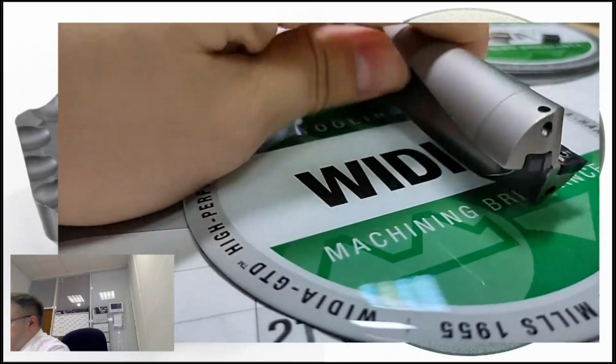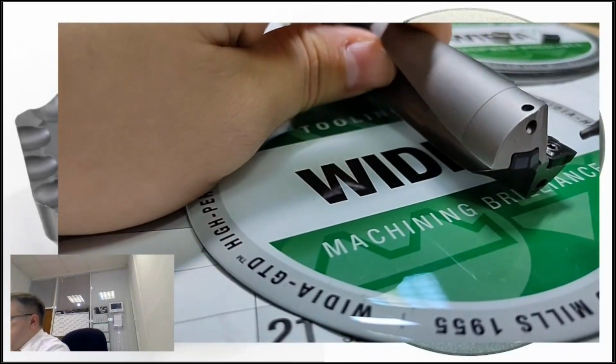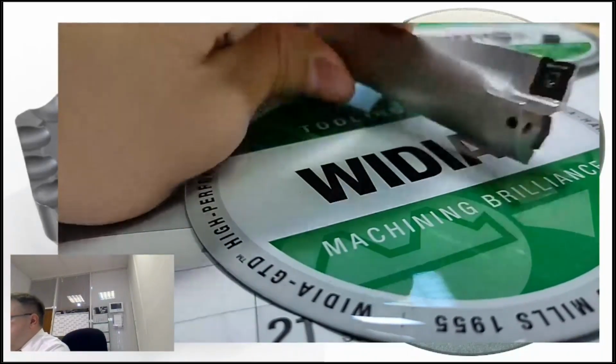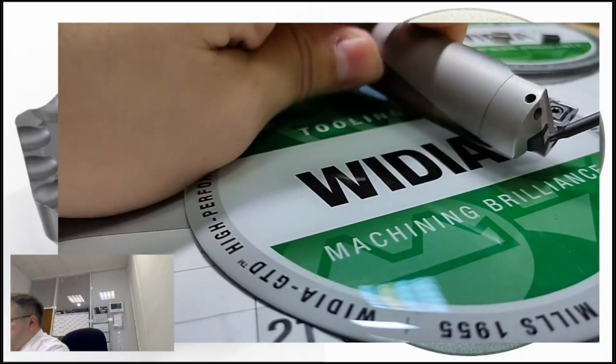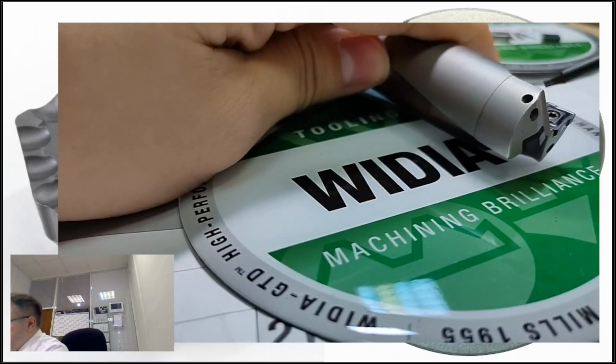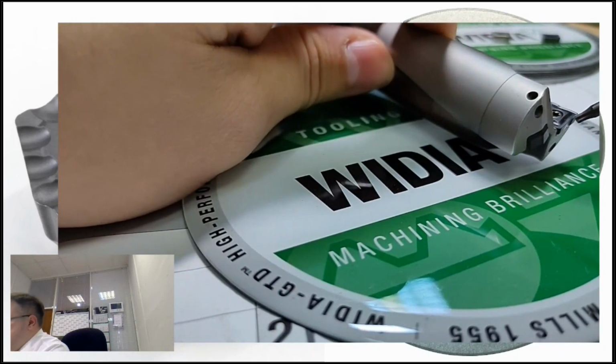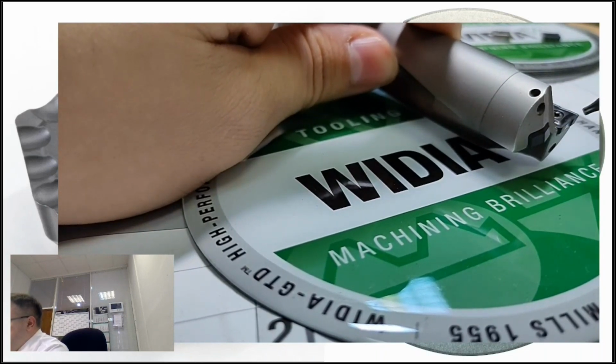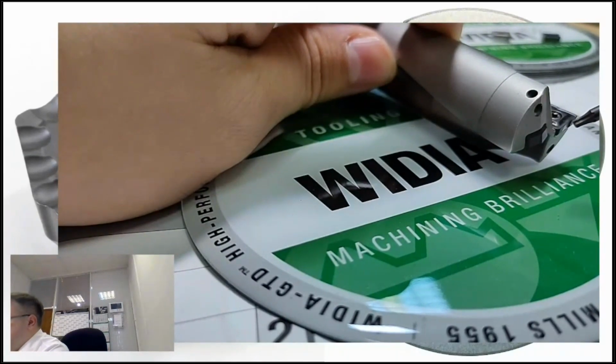So basically you can see these drills look like drills with two cutting edges, with two teeth, but in reality it's one tooth. These inserts are put in different positions, and between them there are edges for different reasons: because of the production of inserts, to have 4 cutting edges, to concentrate cutting forces in different directions, and to give this drill the ability to be self-centered during the drilling process.